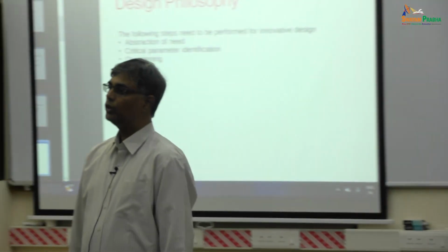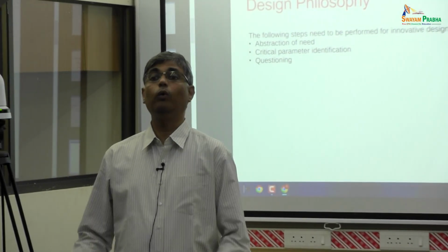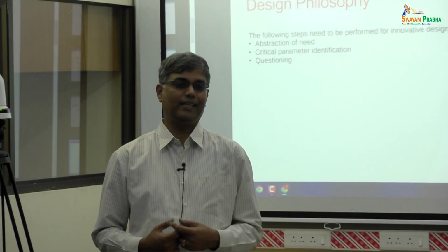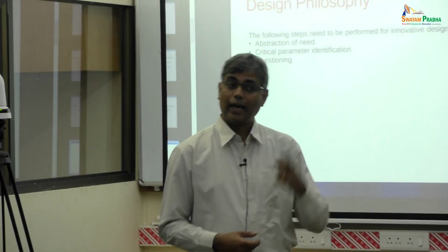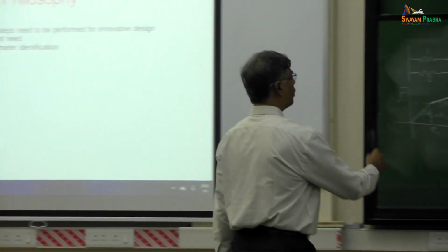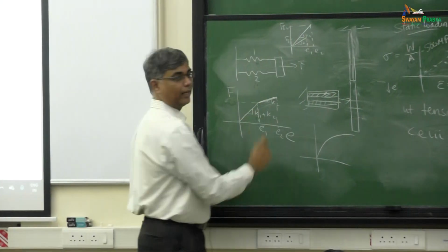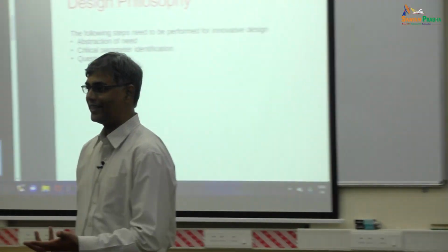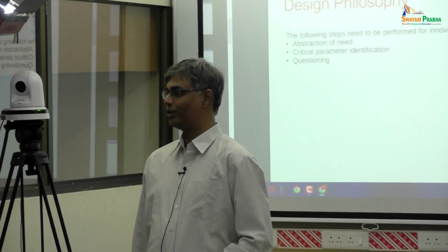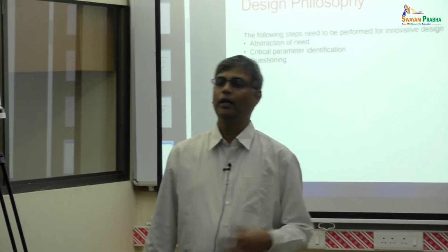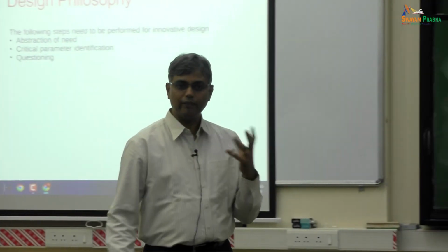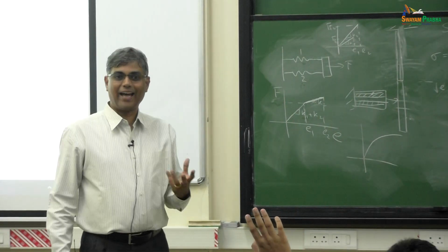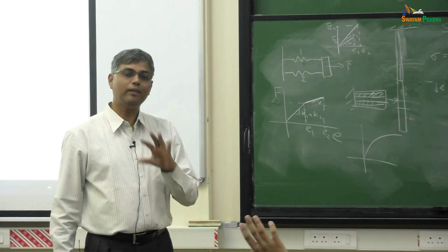So that means there's a certain amount of inelasticity. It's no longer an elastic curve. Elasticity means you have to follow the same curve in loading and unloading, whereas here there is some permanent damage that has occurred. Therefore, it follows a different curve. So this is a very simplistic model. There might be some aspects which will not be exactly the same as what you would expect in real life, but that's okay.